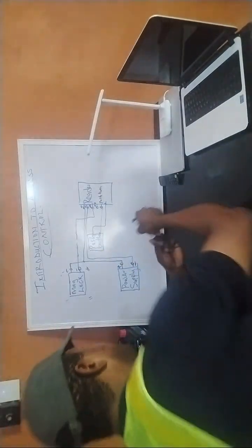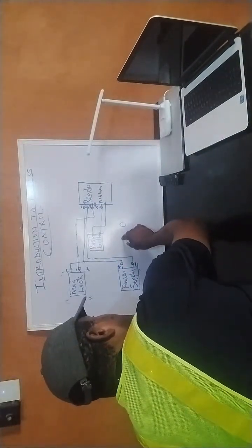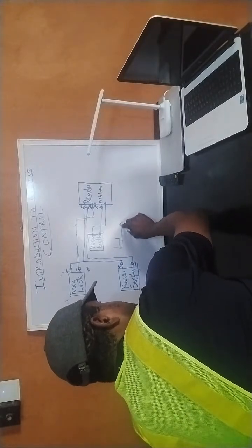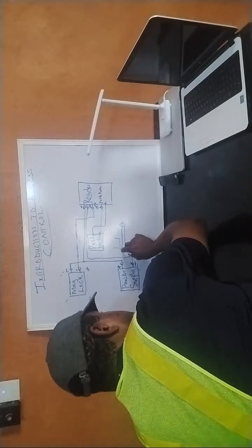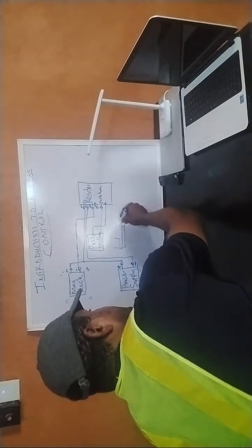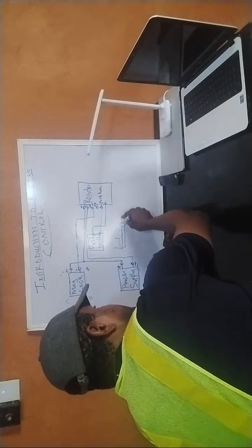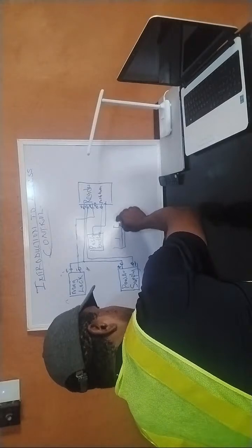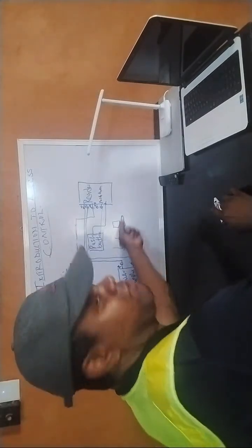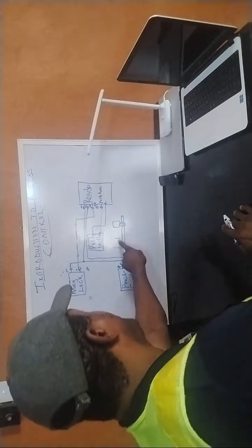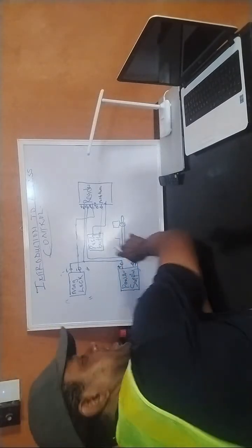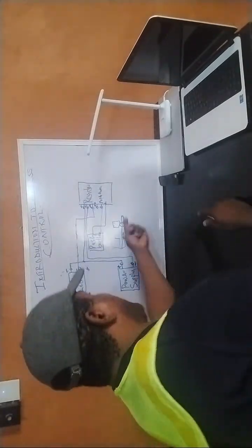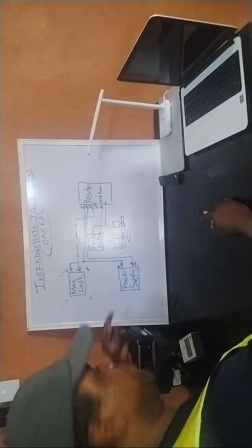Just like maybe I have this hole, let's say this is my lock. This thing is supposed to go into this and lock. Let's assume this is going inside this, this is the full length of it, and this is the hole. Let me assume this is supposed to be a strike or a deadbolt. So when there's power in this magnetic field here, it will draw this back, pull it back from this.